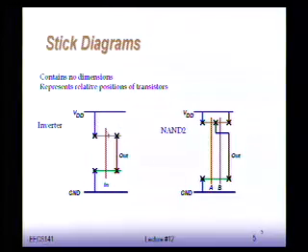What this also specifies is that the NMOS and the PMOS have the same orientation. They both have the gate orthogonal to the supply rails. And the gates are connected directly in poly, so there is no gate connection. And this is done to minimize area, really, and avoid the contact.